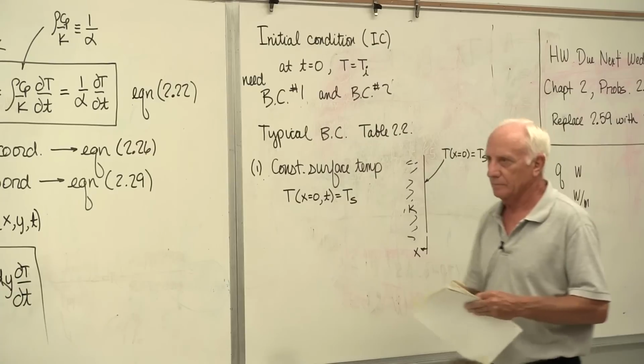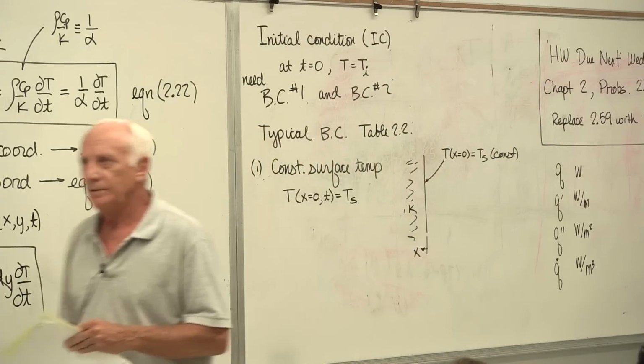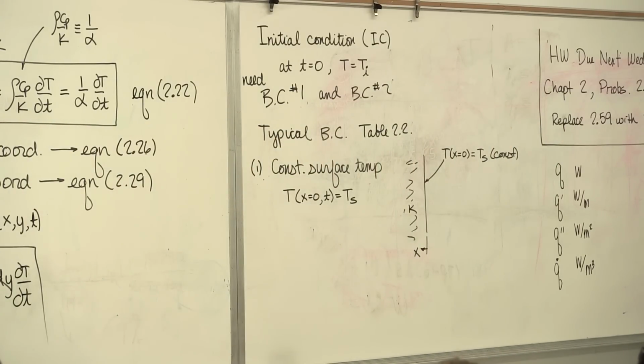You could probably treat that wall right here as a constant temperature wall. I guarantee you the outside wall is hotter than the inside wall right here. So if I'm going to analyze this wall by conduction, the wall outside, especially in the afternoon when the sun hits that wall, the outside temperature is warmer than the inside wall.